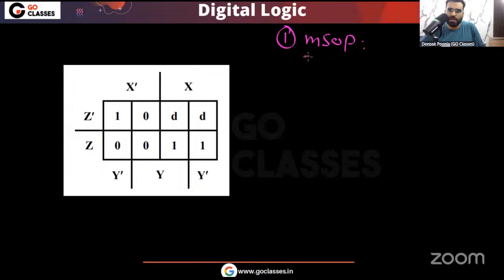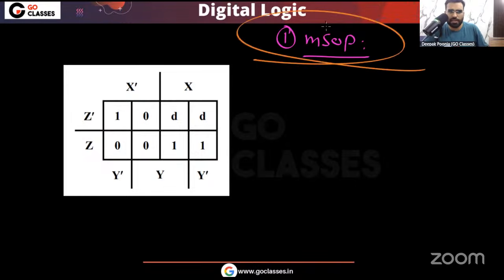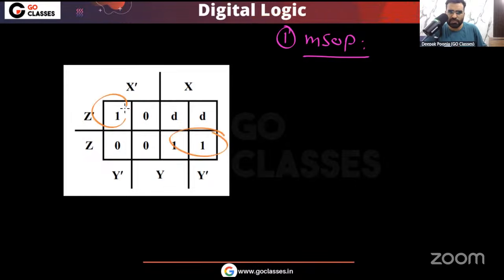Let's find the minimal SOP expression. To find it, we are going to cover all the 1 cells. Here you can see these are the 1 cells. We need to cover all the 1 cells with a minimum number of cubes, every cube as large as possible. And remember, we don't care about don't cares: we may cover them or we may not. If you get a bigger cube by using don't cares, then you can use them. Otherwise, you don't have to worry about them. To find the minimal SOP from the K-map, we just need to cover all the 1 cells with a minimum number of cubes and every cube as large as possible.